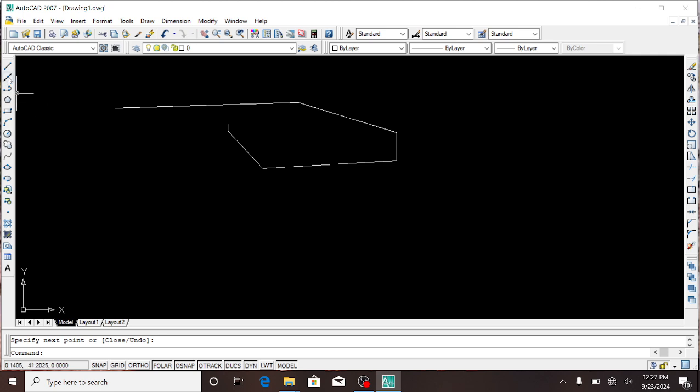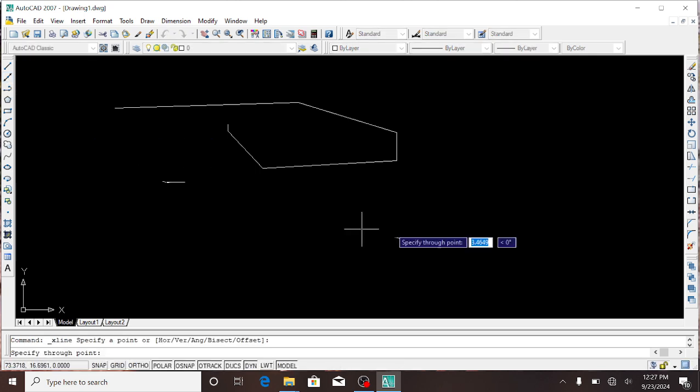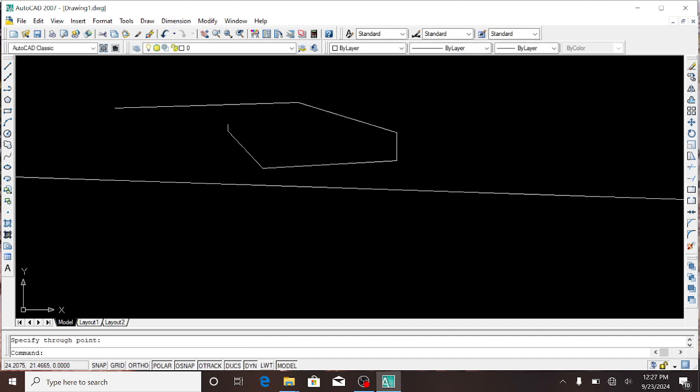The next thing is we have the construction line, which if you want to draw, you can also just place it and AutoCAD will realize it. Then the next one, we have the polygon. You can draw any polygon, 4-sided, 6-sided, all of which you can draw using these tools found in the drawing toolbar. Then we have the rectangle. If you want to draw a rectangle, it's just easy. You select, you click the opposite side and the other opposite side, then the rectangle is produced.